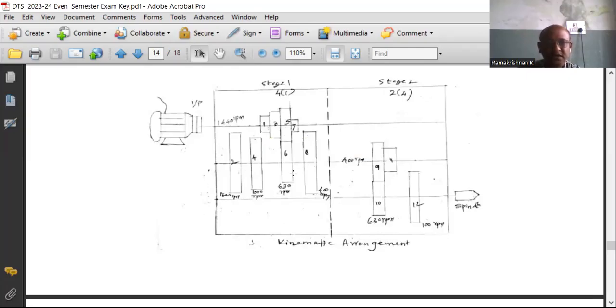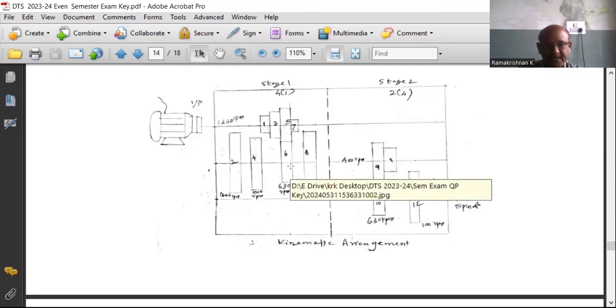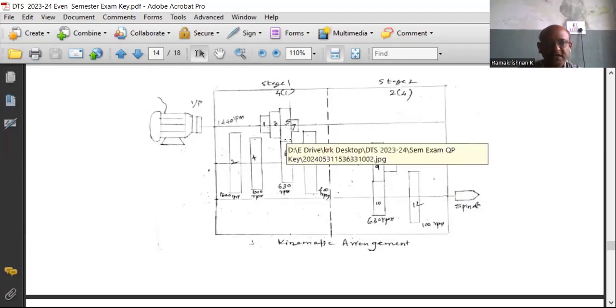Then you also draw the mating gears. For the 4 gears there should be the output, so there should be 4 mating gears. Now you join with 5 as the largest gear. Now you draw the mating gear 6 as per the diagram. It should be meshed. The other 3 gears are drawn in line with the other 3 gears 1, 3, 7, so that the gears can be slid to have the proper mesh.